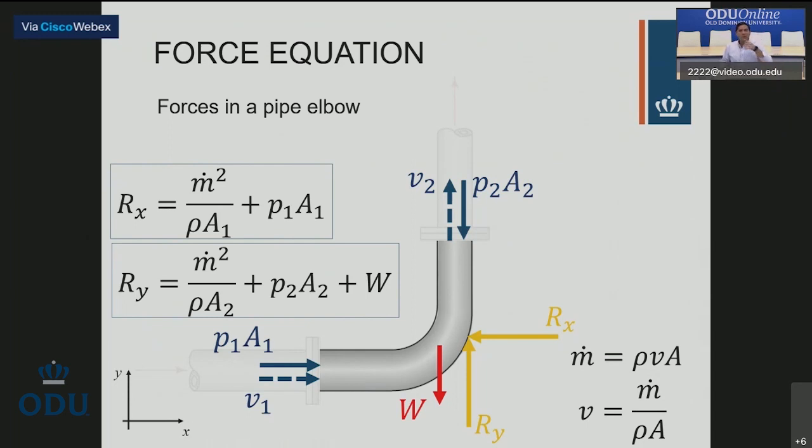Now, this is how we use the force equation. And what we just did, that's what engineers do to design the wind turbines. Exactly that. The difference is that in the interaction between the wind and the blade in the wind turbine, the V1 and V2 are not changed 90 degrees, because you're not going to see the wind blowing and changing direction 90 degrees. The changes are subtle, 20 degrees, 30 degrees at the most. You will see certain change, but not that much.